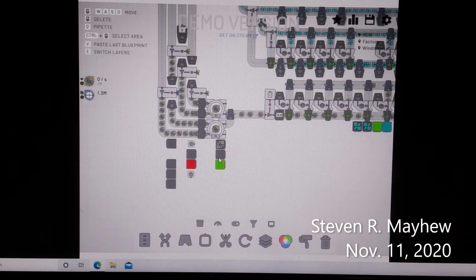Now this signal shows red when either this receptacle is empty or these two overall shapes do not match. It shows green when they do match. And again, using a series of XOR gates, I can control the same input with this switch or the one that I turn on the other end, or others which are way up above.